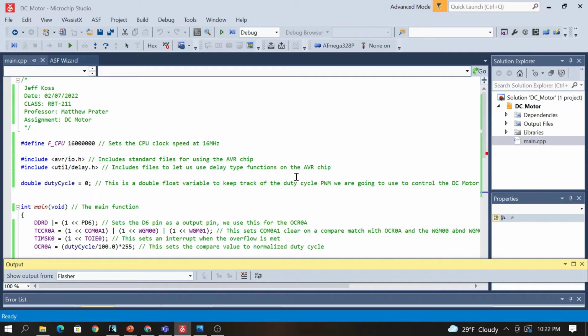What we had to do is use pulse width modulation on an AVR chip. I'm using the 328P. It is hooked up to an Arduino, but only for power source reasons. I'm programming this using Microchip Studio, directly to the AVR chip itself using straight up C, and we're using the libraries that come with the AVR, not the Arduino.